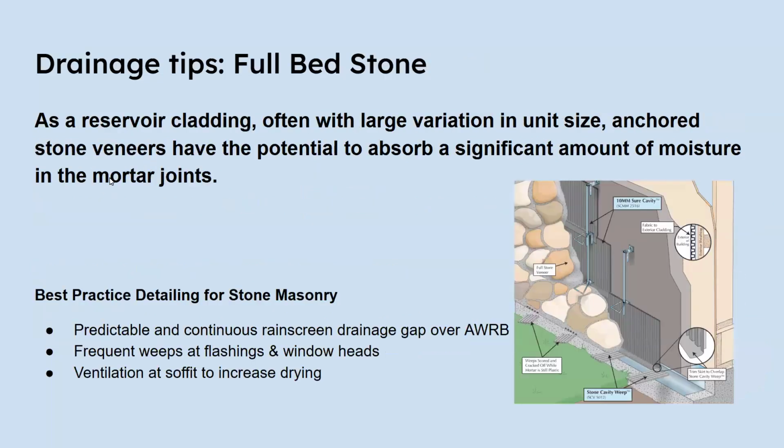Full bed stone falls into that same category, except it's thicker stone. Again, it's a reservoir cladding. Moisture is going to go through it. You're going to want a space between the rain screen behind it and, of course, weeps at the bottom.